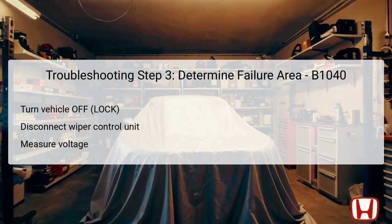In this step, you will determine the potential failure area by measuring the voltage around the windshield wiper control unit and motor. Begin by turning the vehicle to the off, lock mode. After this, disconnect the 6P connector from the windshield wiper control unit.